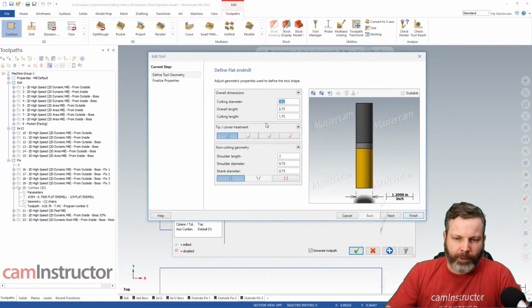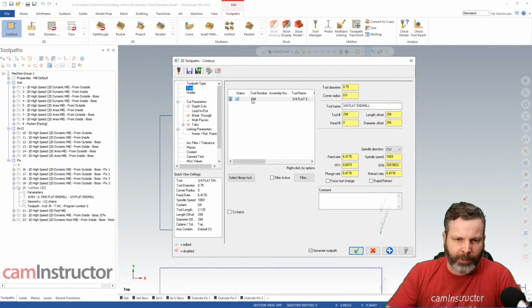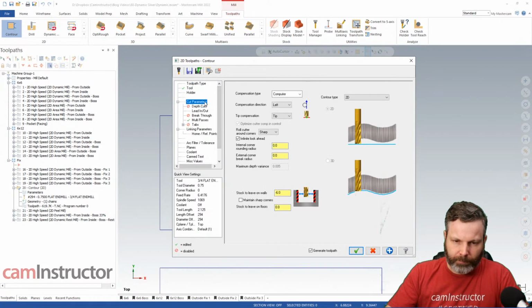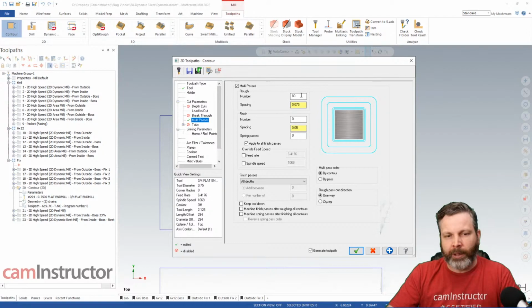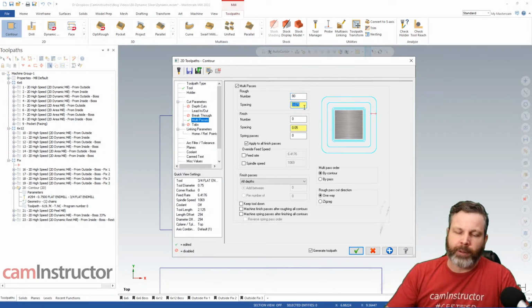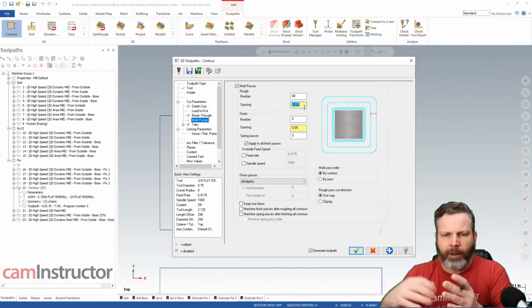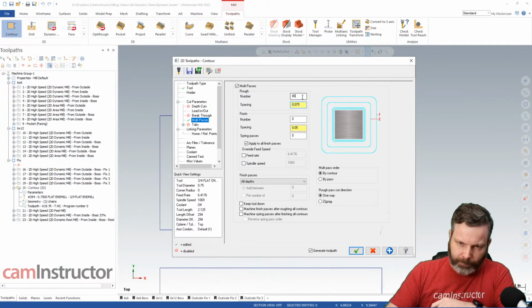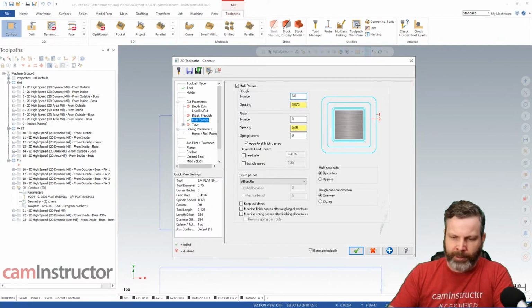again, it works fine. Oops, my speeds and feeds aren't coming through here. There we go. Yeah, so you need to figure out how much you need to overcut it, and then you have to come in and calculate the number of passes you need and the step over for that. So the step over we already know it's the 75 thou that we wanted to maintain that 10% engagement, but we would need to take our 6 inches divided by 75 thou, and that's what gives us our step over there.